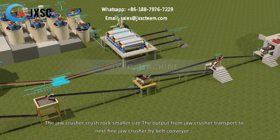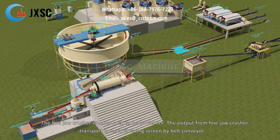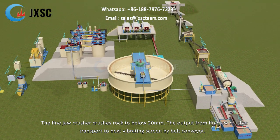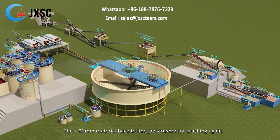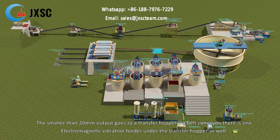The output from the jaw crusher is transported to the next fine jaw crusher by belt conveyor. The fine jaw crusher crushes rock to below 20 mm. The output from the fine jaw crusher is transported to the next vibrating screen by belt conveyor. The material larger than 20 mm goes back to the fine jaw crusher for crushing again. The material smaller than 20 mm goes to a transfer hopper via belt conveyor.